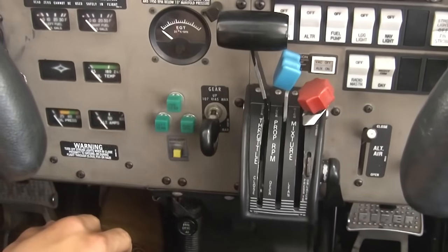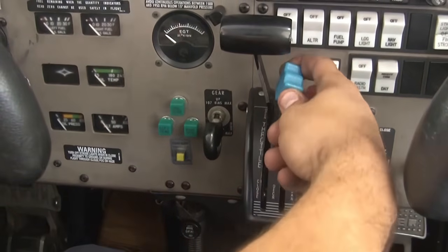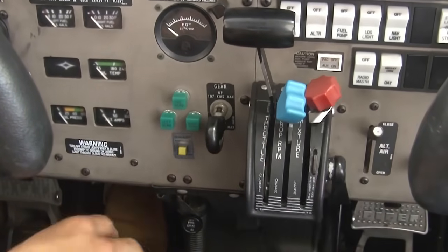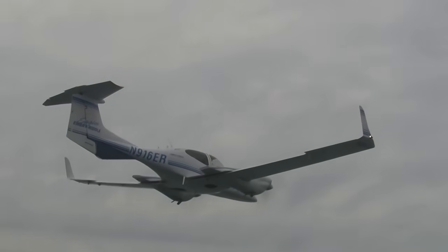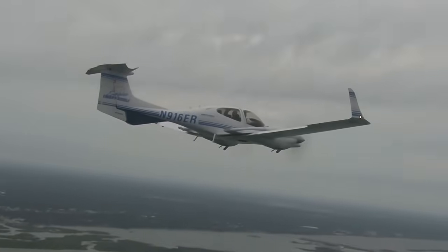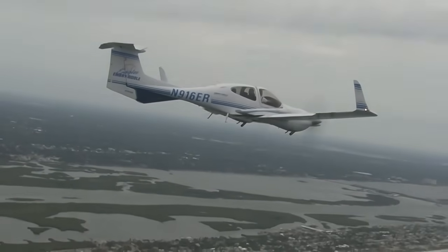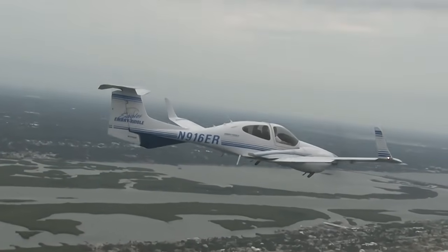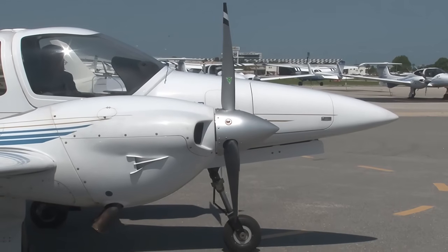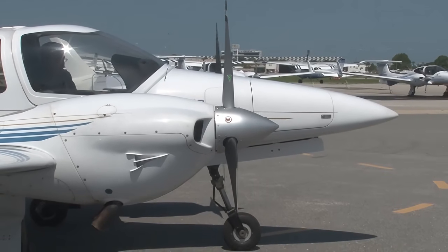This control, which is usually blue in color, allows the pilot to change the RPM of the propeller instead of just based on the engine's output. The reason this propeller is called constant speed is that when throttle movements are made, the RPM, or speed at which the propeller is rotating, will remain the same. This is accomplished by rotating the angle of the blades, which allows them to deflect different amounts of air.